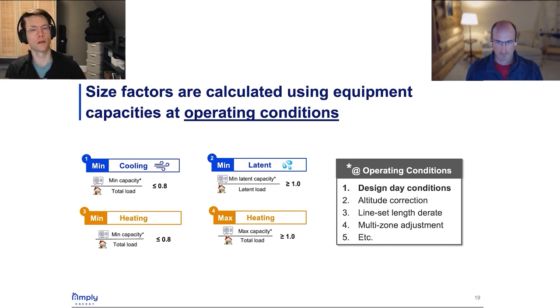This all makes sense. Also, you keep saying it's straightforward. The more straightforward steps you layer onto something, the more complex it gets. This is a decent number of steps, but my takeaway here is, for the operating conditions, are you picking equipment for heat pumps that are going to be able to serve both the needs of winter and summer? And as we know from previous episodes, there's a direct trade-off there, right? Because if it's too big, just like our climate zones, I'm in Massachusetts, you're in Maine. If you oversize something for the winter, it's probably not going to ramp down low enough in the summer because the winter loads are so much higher, the heating loads are so much higher. And so you're going to have trouble removing that latent capacity.